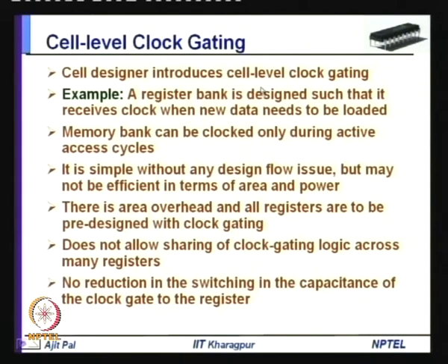by the cell designer. So, for example, a register bank is designed such that it receives clock when new data needs to be loaded. So, the register bank is designed in such a way, the functionality is built in such that the clock will go there only when new data has to be loaded.